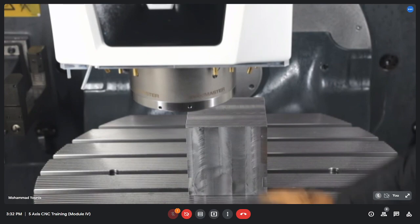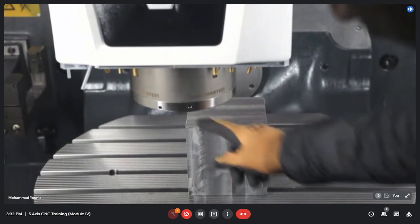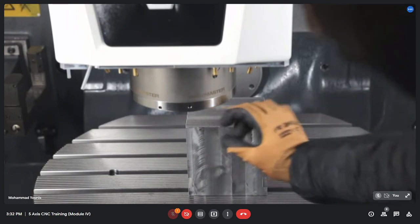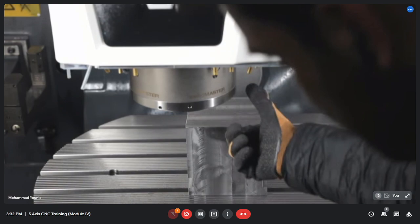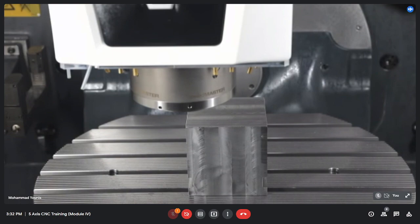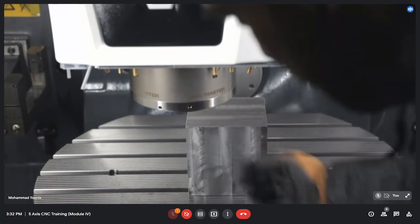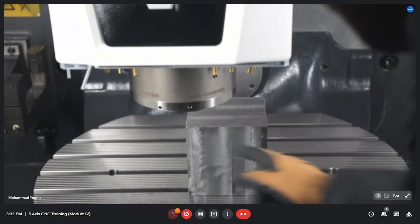The movements will be from this corner. This time we have x and y at 0 0 and z at 50 mm. So here you can see there is a 50 mm gap from the top surface. Now if I give a value of positive 100 mm in the x-axis, the tool, or the axis of the spindle, is going to move in this direction, in the positive direction.